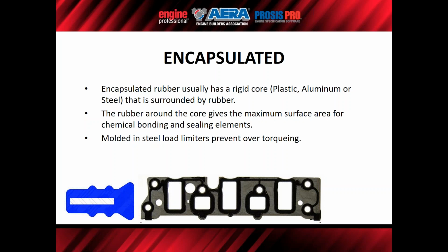usually that pitting occurs where the bead is in contact with the flange, kind of like you see on a crankshaft. You got that front crankshaft seal that rides on the shaft and it wears a groove in it. It's kind of like that, but it's pitting caused by electrolysis right where the bead was, and sometimes outside of that. And these extra beads provide that insurance to overcome that pitting.